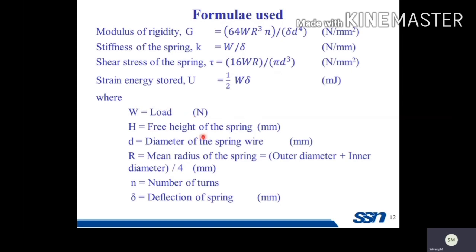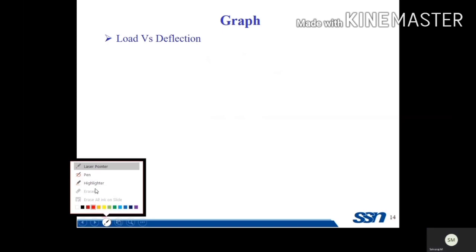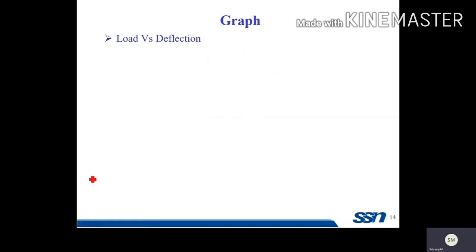So now we have all the details. For every reading, you calculate the modulus of rigidity, stiffness, shear stress, and strain energy stored. After the calculations, you draw the graph. In the graph, you have to draw the graph in between...